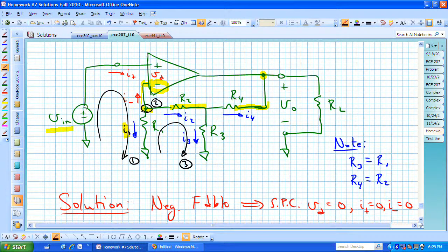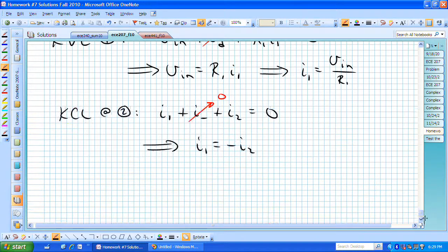That will be plus I sub 3 R sub 3. We will then do KCL at 4, and finally we'll do one last KVL equation around 5, and we'll go up through or against I sub 3. It'll be minus R sub 3 I sub 3 plus R sub 4 I sub 4 plus V naught is equal to 0. That's what we want to do now, and then we'll eventually be able to solve for V naught in terms of the currents.